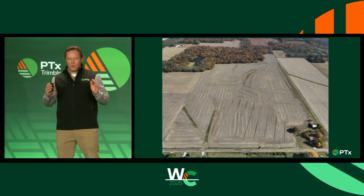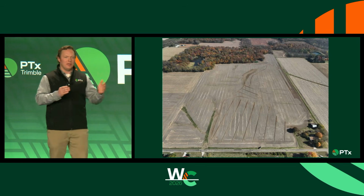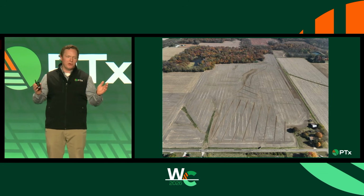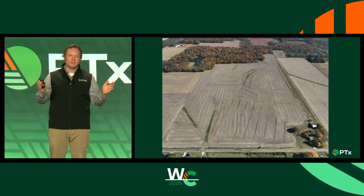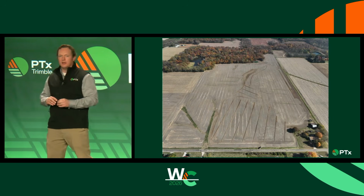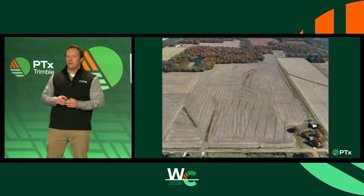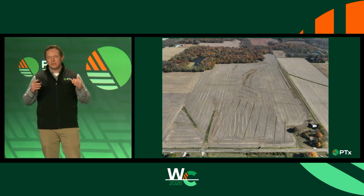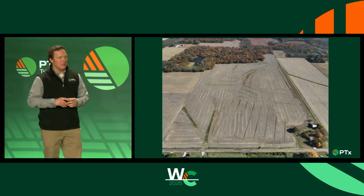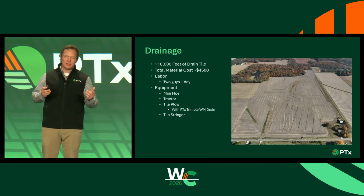And so in 1 year, using data other than our yield map, we went in and tried to fix this farm. Now, did we get it perfect? It's probably not. But did we get 95% of the problem fixed? Probably. If we need to go back in and add a line 5 years from now, we can do that. But what we tried to do is use the data that we have to fix it before it becomes this big yield drag. And so in this case, on this farm, we ended up adding about 10,000 feet of tile.